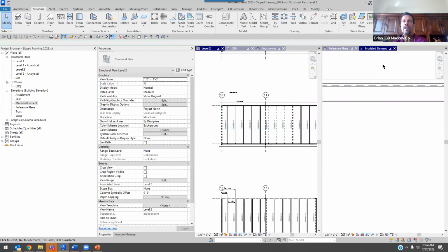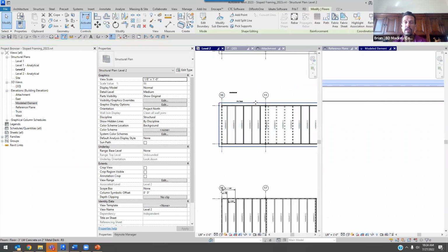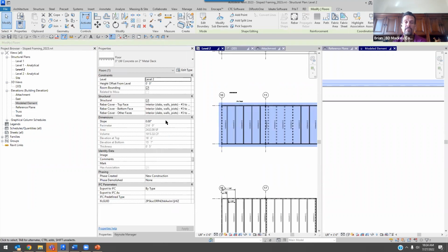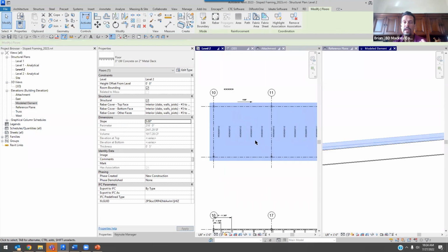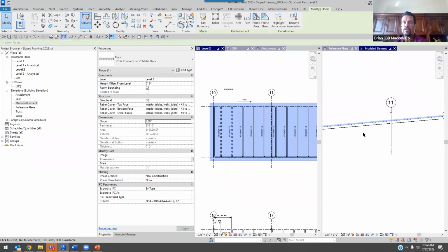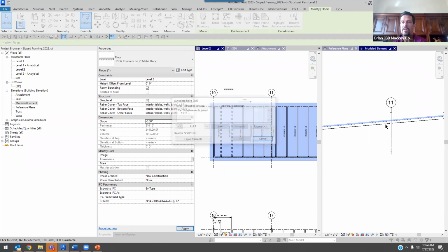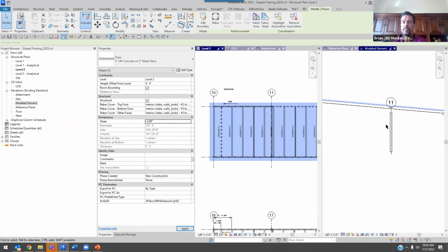So now, rather than having to go into that vertical view and rotate it, since I've got this roof defined as a slope, I can put that 5-degree slope on, boom, it's going to go through and say, hey, look, now we're sloping. Make it a -5 degree if I needed that to go up, whatever is going to be true, unjoin, and then it's going to come through and set it up.